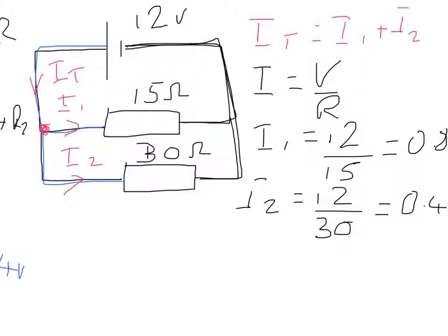Right, that leaves us one thing to look at for this parallel circuit, which is the effect of combining two resistors in parallel. So if you look at this circuit, you can see that because we've got more pathways for the current to flow through, more current is flowing, which means that the combination of these two resistors gives us a lower resistance than each of the individual resistors on their own.